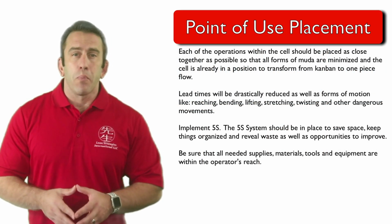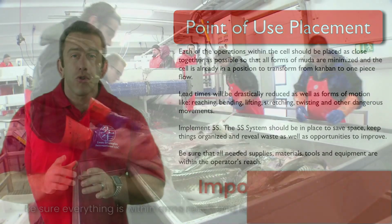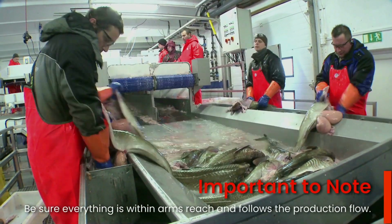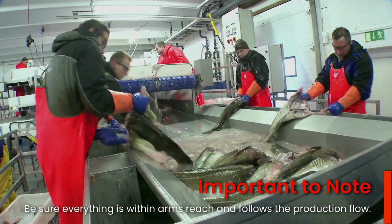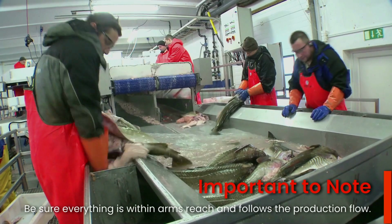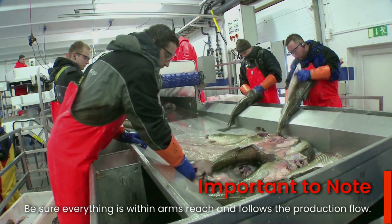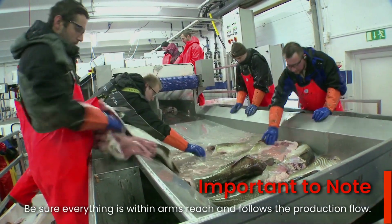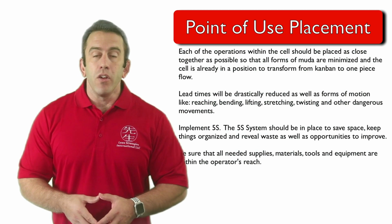One last thing before we move on. As you place your operations in a process flow layout within a cell, be sure that all needed supplies, materials, tools, and equipment are within the operator's reach. They should also follow the production flow of the materials or information so that they can flow in and out very smoothly. And that's it. Point of use placement within a cell.